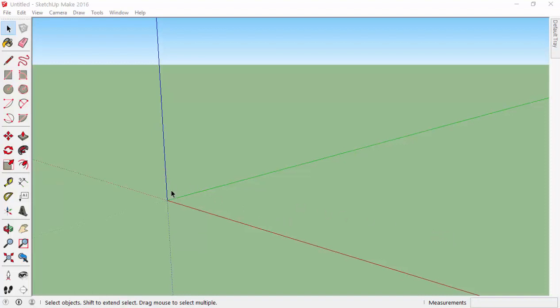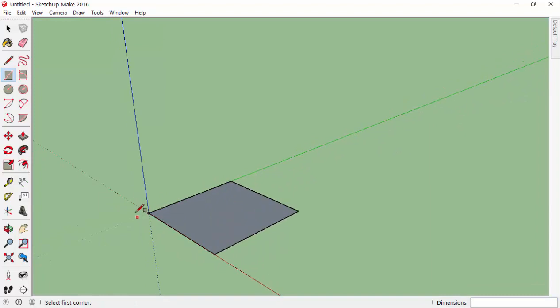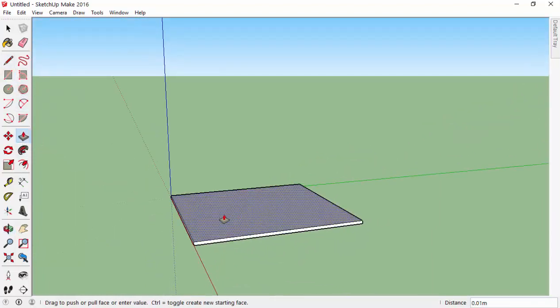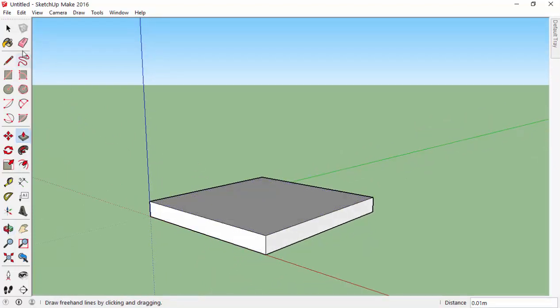Today we're going to make a chair, a perfect chair I call it, because I put more details on that one. Firstly, we're gonna make the basement of the chair quickly by getting the rectangle tool. If you want, you can also work with specific dimensions such as 0.52, 0.5. Okay, and I will zoom in, and then I'll give it a little bit of thickness, by using the push and pull tool.